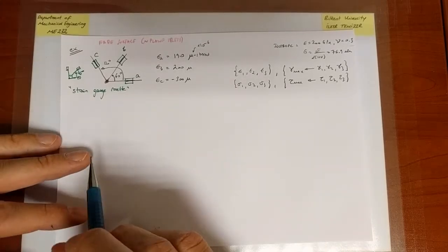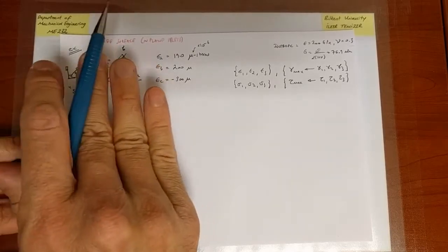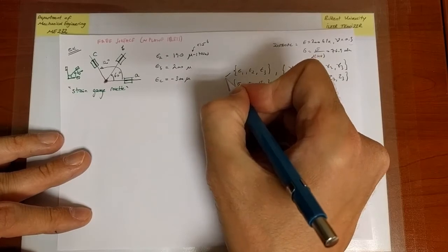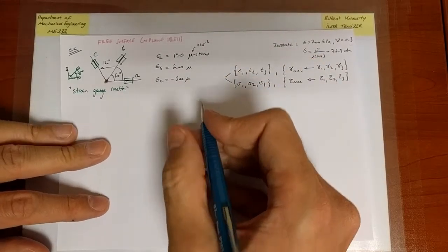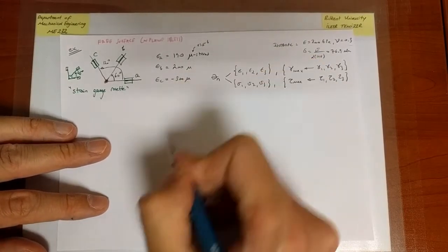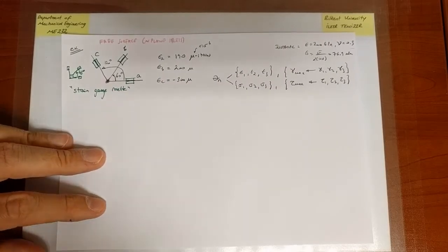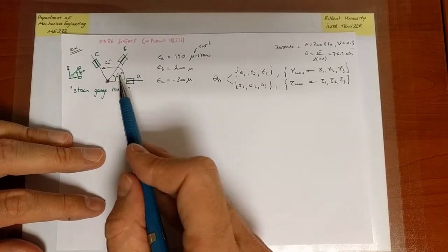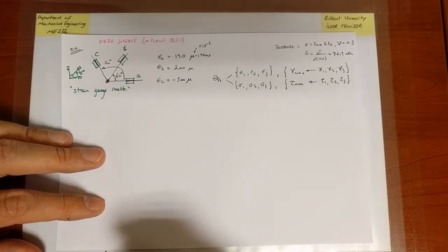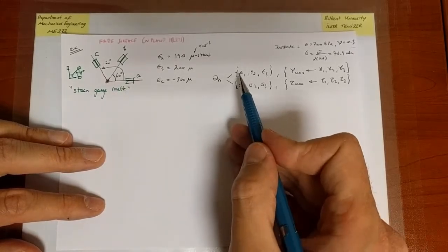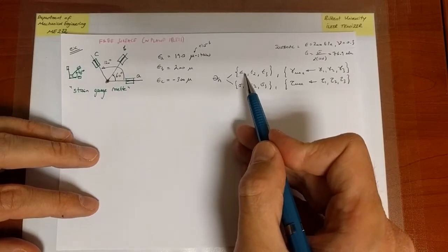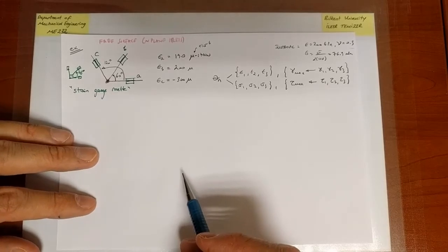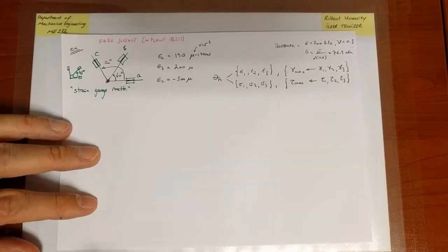It would be sufficient to know only one. We know that we have a generalized plane stress and a generalized plane strain, so there would probably be one angle associated with this. That would be sufficient. Let me call that theta, and only the angle associated with the rotation from the original picture to the principal stress picture. That angle is the same as the principal strain picture, because remember, principal directions are the same. I've stated without proof. So if I provide all of this information, I will be done.